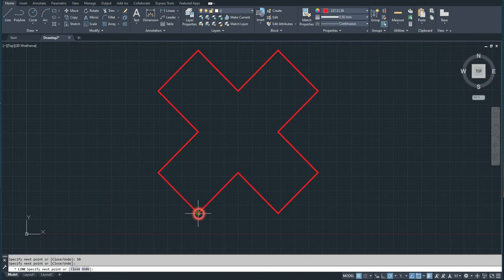If I want to do the same example, guys, using the angular dimensions, how can we do it? Draw a line. Say I will start from here, guys. Okay, let me choose a yellow. Draw a line from this point. Let me disconnect the polar tracking. Now we can't see anything, guys. Okay, see, there is no polar tracking.